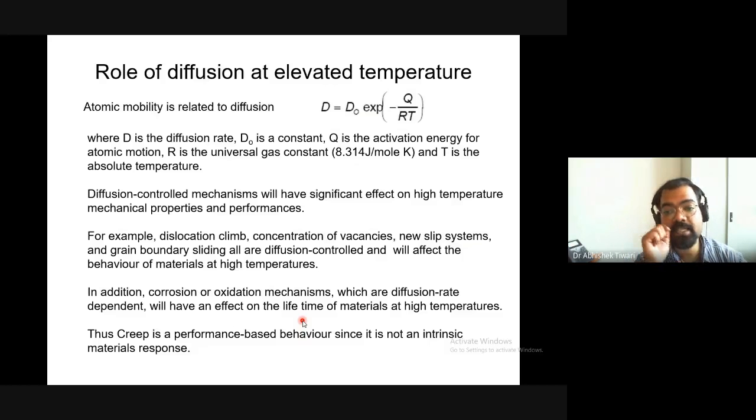So this is why initially, when people used to do fracture mechanics tests, they used to put dye at the crack tip, right? Because you want to know from which point to which point the crack has increased. So they used to put a dye, and then the crack has increased, so you know that this was my initial point, because the dye will color, it will mark the initial position, and then you know the final position, so you can find out what is the crack length.